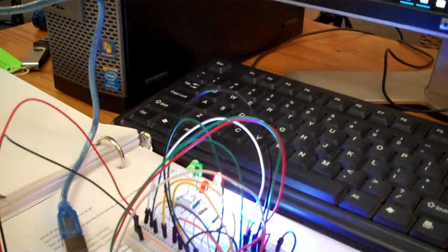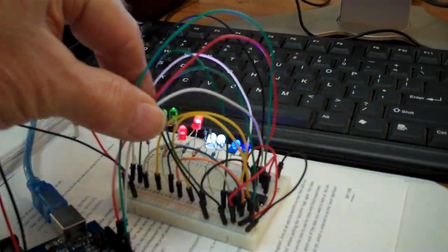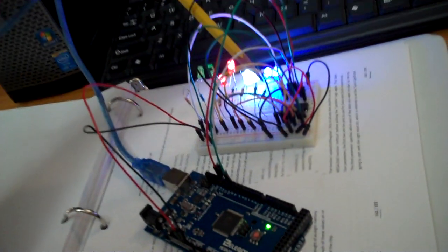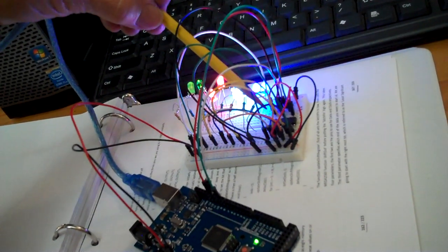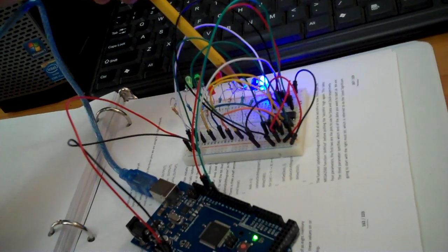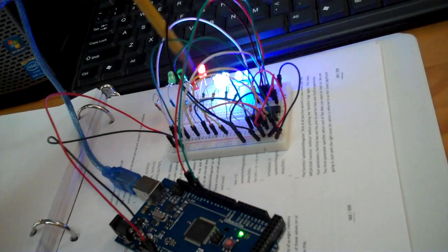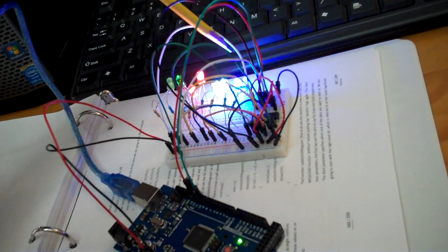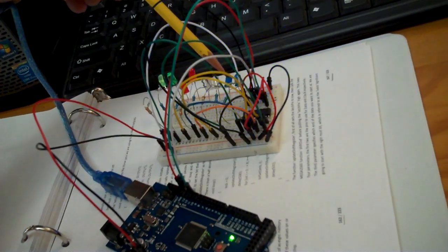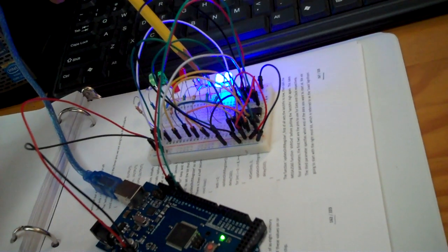Taking a look at the circuit itself, we can see that the three signals, which are right here, for the latch, the clock, and the data, are coming out of the microcontroller board here. As it goes through the IC chip, which is the 74HC595, its outputs are driving each one of these LEDs to a logic 1, which is going to indicate its operation. Once it's already set to logic 1, it goes to the next one.